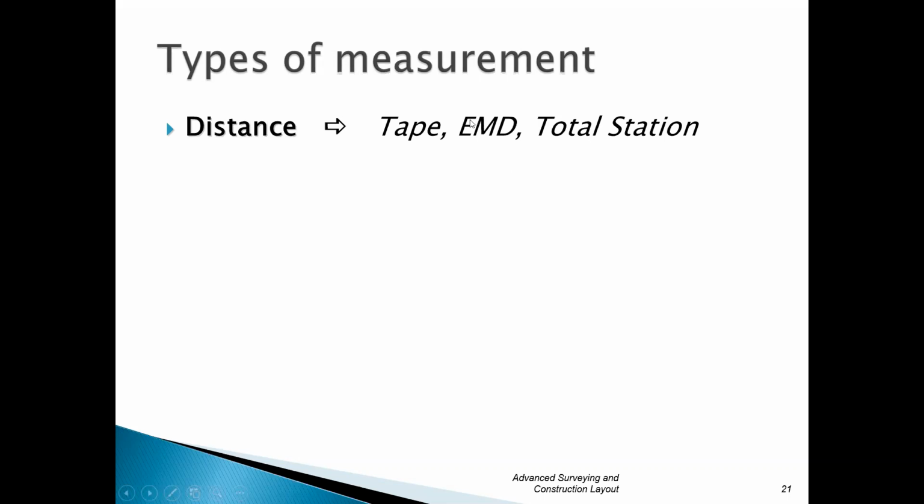Back in the older days, the 70s and 80s, a lot of people had an instrument called a theodolite, which would measure angles, but it wouldn't give you distance. So you either had to use a steel tape and a theodolite, or you could get a unit called an EDM that would sit on top of your tripod and shoot the distances separately. That was a much harder process. But these would be the primary methods. And from a layout standpoint, nowadays most people are using the total station.